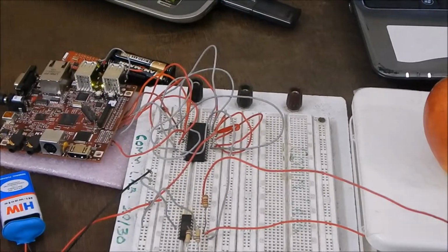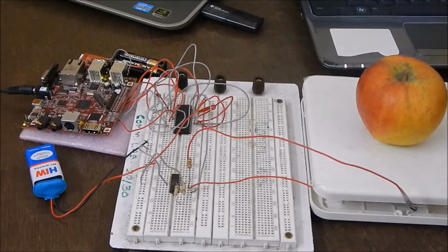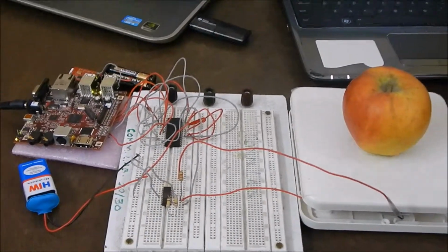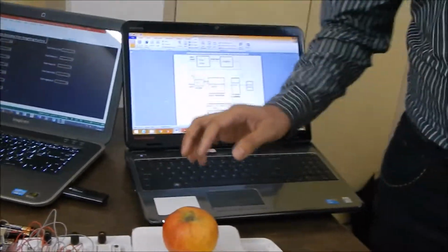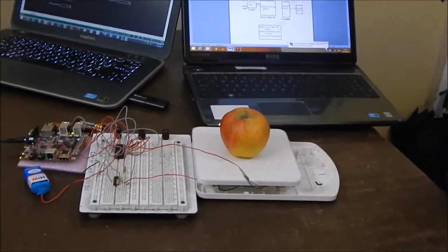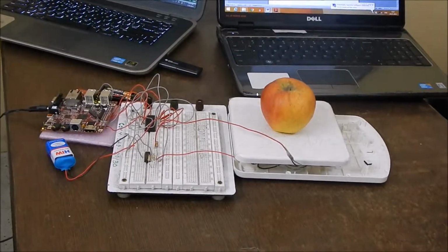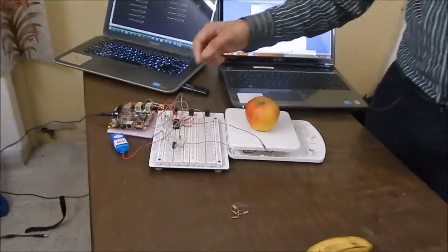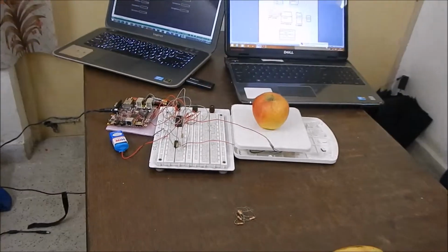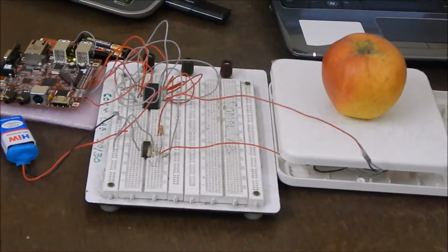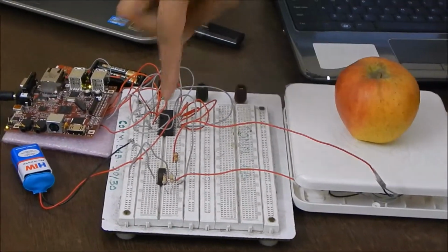As we know, the voltage signal is a very small analog signal, so it needs to be amplified. For amplifying, we use an operational amplifier, using the IC OPA4228, and we have used an RF by R1 ratio equal to 2000, which will give us a gain of 2001, and this is the circuit diagram.